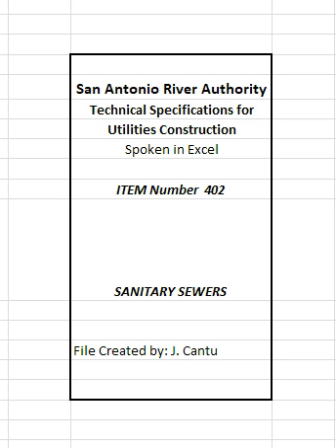The sample well shall have a riser a minimum of 6 inches in diameter and shall be installed after the confluence of all waste streams from the facility and prior to discharging into sanitary sewer collection system. The well shall be perpendicular to the effluent lateral to allow visual observation of the flow stream and provide for sampling of wastewater.